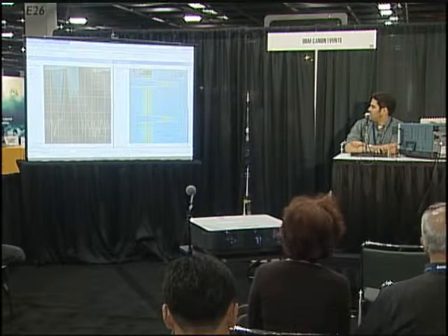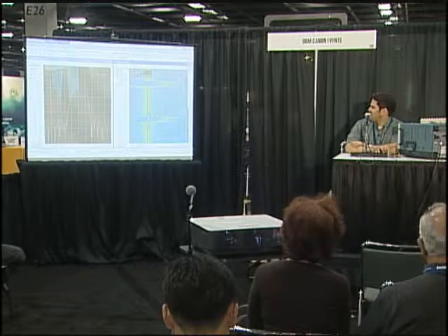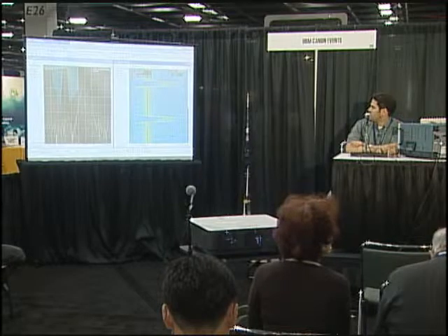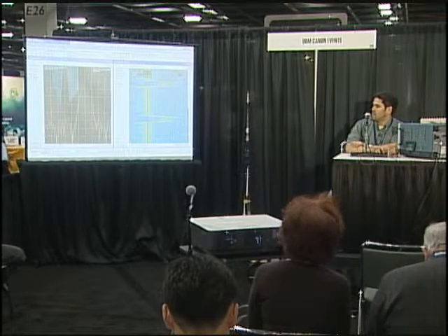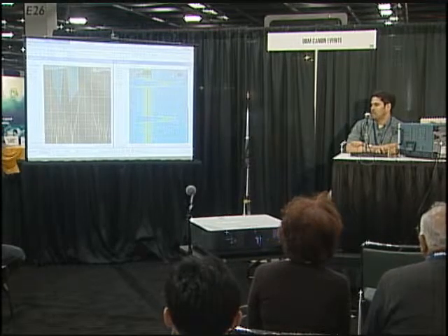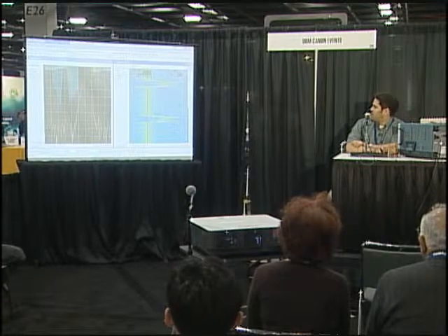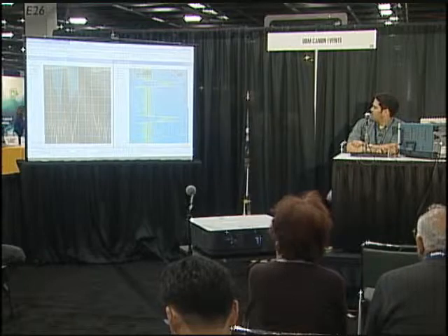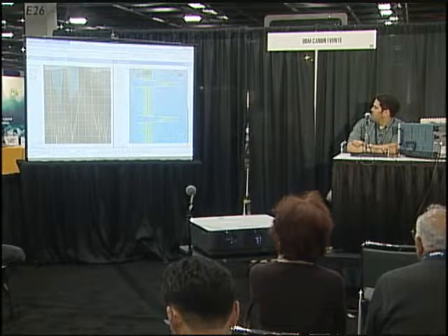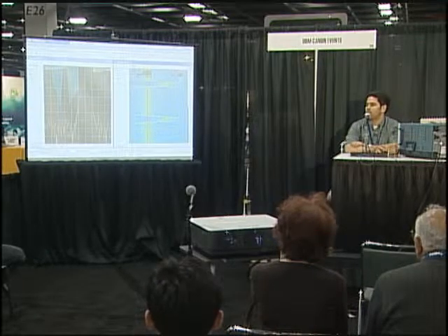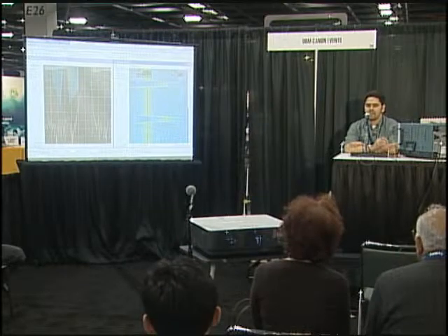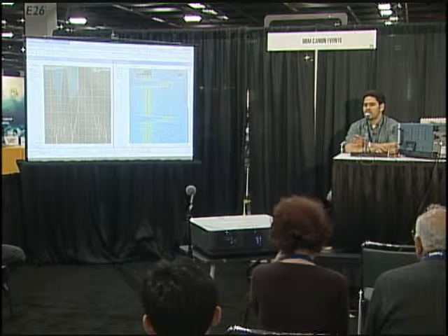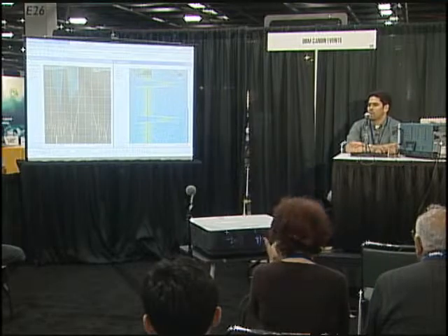If now I put a delta marker between here and here, now I get the repetition time between these two events, and it's about 1.28 seconds. So what we did here is we acquire a 1 millisecond from here to here, another millisecond from here to here, but between the two there was a whole 1.2 seconds of activity where nothing happened. So nothing violated the mask during that whole 1.2 seconds.